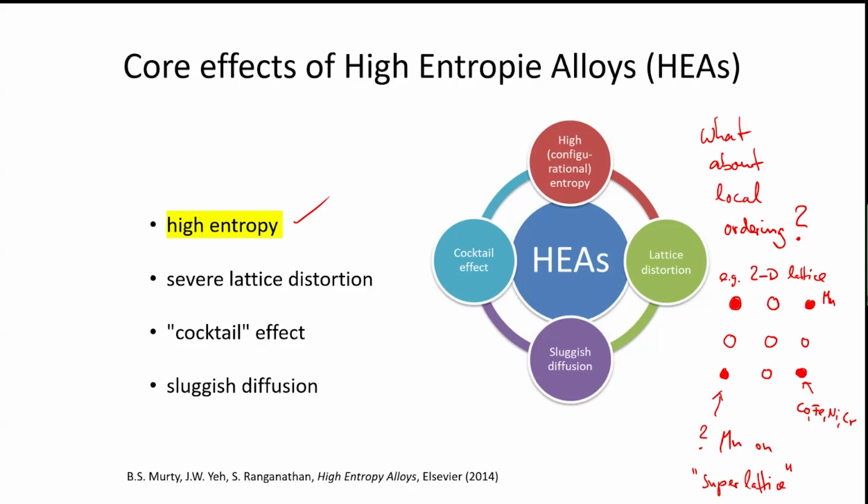Like if it's 1/5 for all 5 elements for each lattice position, then it's correct that you calculate the configurational entropy just by the statistical entropy term. If the occupancy is preferred for some atoms, some constituent on some sites, then it's reduced. Then you are not allowed to do it in this simplified approach, because the probabilities will not be equal for each site and each element.